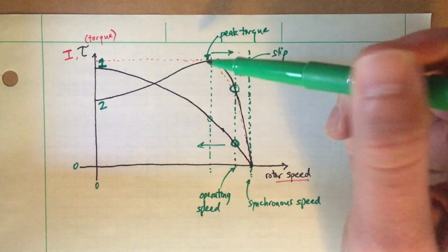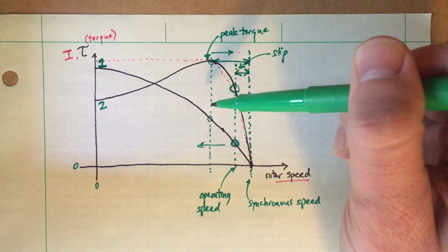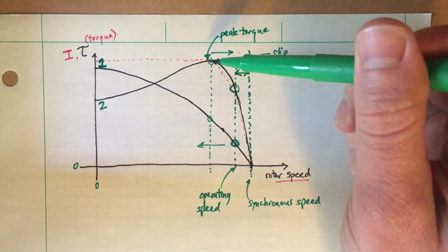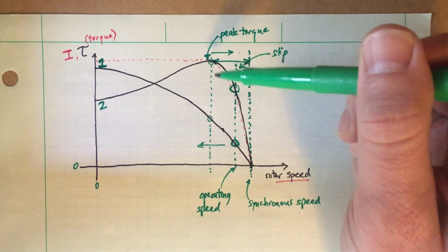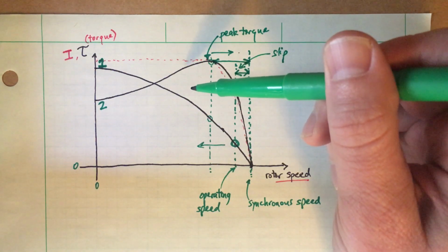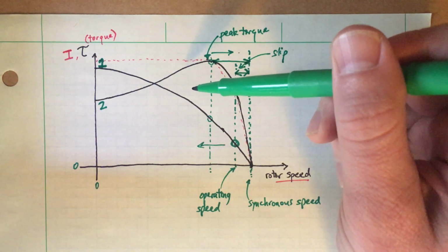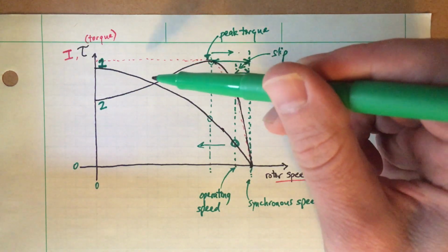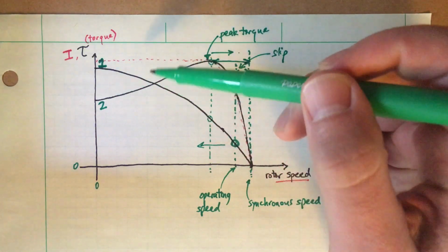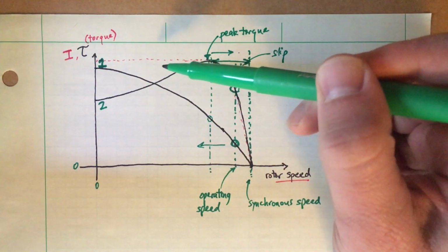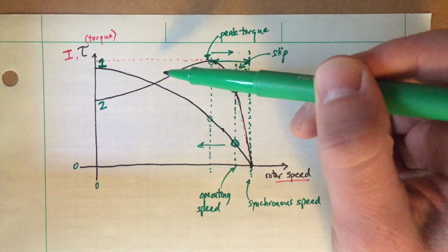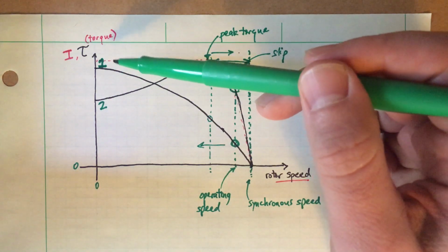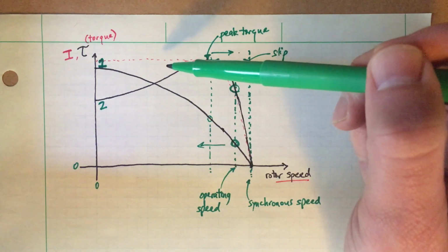Now, in design number 2, well, if you were to drop the speed any lower, with any really big resisting torque that overcomes this maximum torque that it can develop, well, then now you're in trouble, okay? Because if that resisting torque doesn't go away, then the rotor will continue to decelerate. The torque it develops will actually go down somewhat, and yet you'll still have this maximum current going through the squirrel cage, and that can cause damage if that current continues to flow in the squirrel cage bars that way.